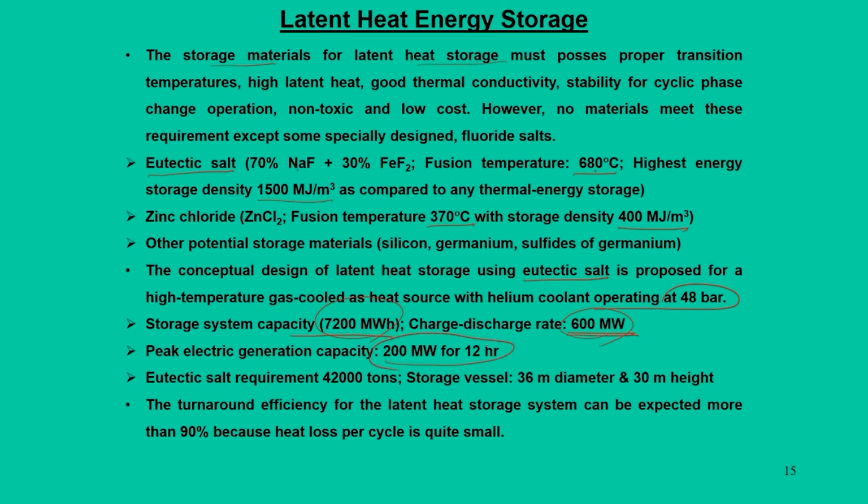And if you want to achieve this with that thermal conceptual circuit, we require eutectic salt of 42,000 tons. Storage vessels will have a diameter of 36 meters and a height of 30 meters.